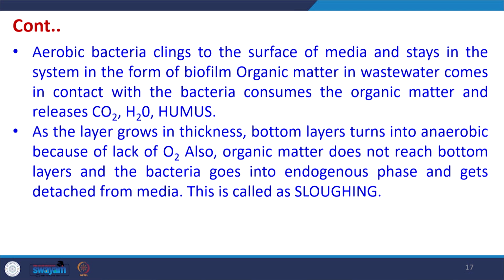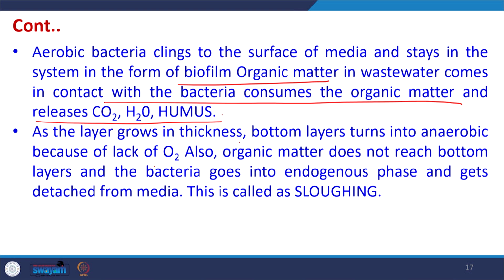If this is an aerobic system, then aerobic bacteria will cling to the surface of the media and stay in the system in the form of biofilm. Organic matter in the wastewater comes in contact with the bacteria, which consume the organic matter and release CO2, H2O and humus etc. In the anaerobic system, we will be generating methane, CO2 etc., and that will come out at the top of the tower and be collected.